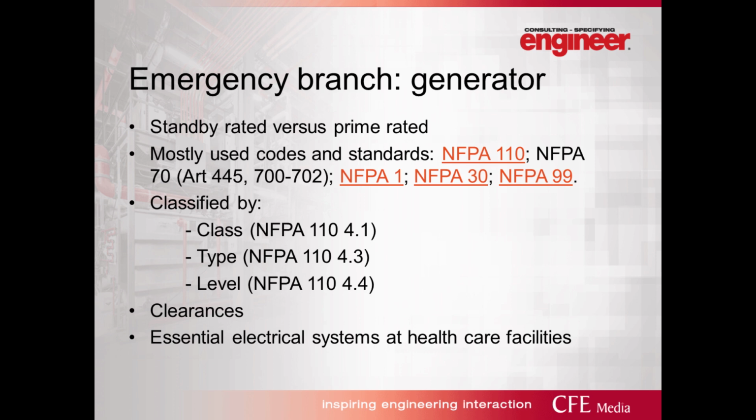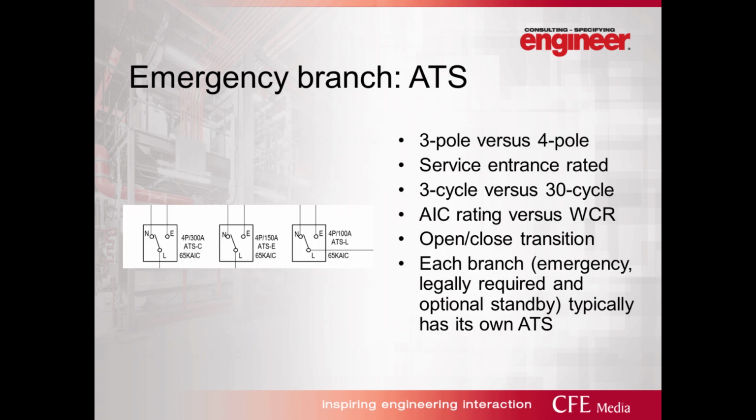The critical branch is more straightforward than life safety. The intent is to provide power for direct patient care. And the final choice for the essential system is equipment branch power. This is where the medical gas equipment or other medical systems can reside. Systems such as operating rooms HVAC, heating for patient rooms, or cooling for data rooms can be placed on a delayed equipment branch power.